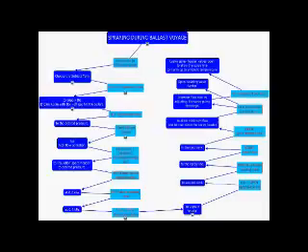Mind that we cannot send the gas to the engine room unless it is plus 25 degrees centigrade. Different companies have different policies, but on average, it is plus 25. So we will have to pull the gas liquid, vaporize it, and then heat it to give it to the engine. Okay, that is the whole process, boil-off management.